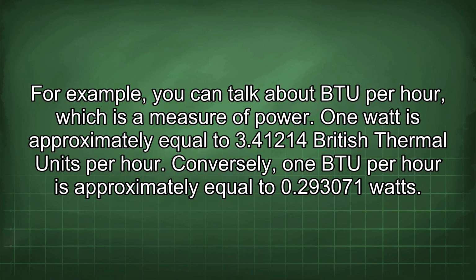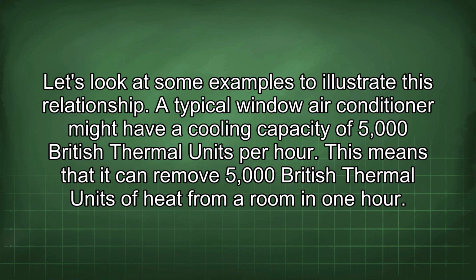For example, you can talk about BTU per hour, which is a measure of power. 1 watt is approximately equal to 3.41214 British thermal units per hour. Conversely, 1 BTU per hour is approximately equal to 0.293071 watts. Let's look at some examples to illustrate this relationship.